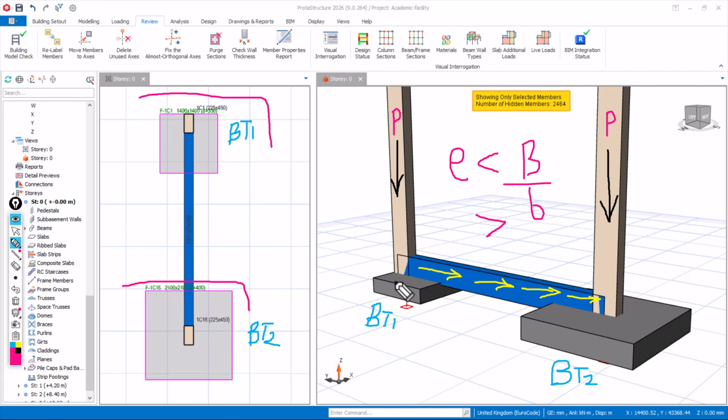And in combined footing design, when a footing is at tension, what do we provide? A top reinforcement, making it a doubly reinforced section. But in this case of an eccentric footing, even if you provide a top reinforcement, it will not be able to counter the effect that this load is causing, an uplift. So what do you then do? It is now the time that you have to provide a strap beam.